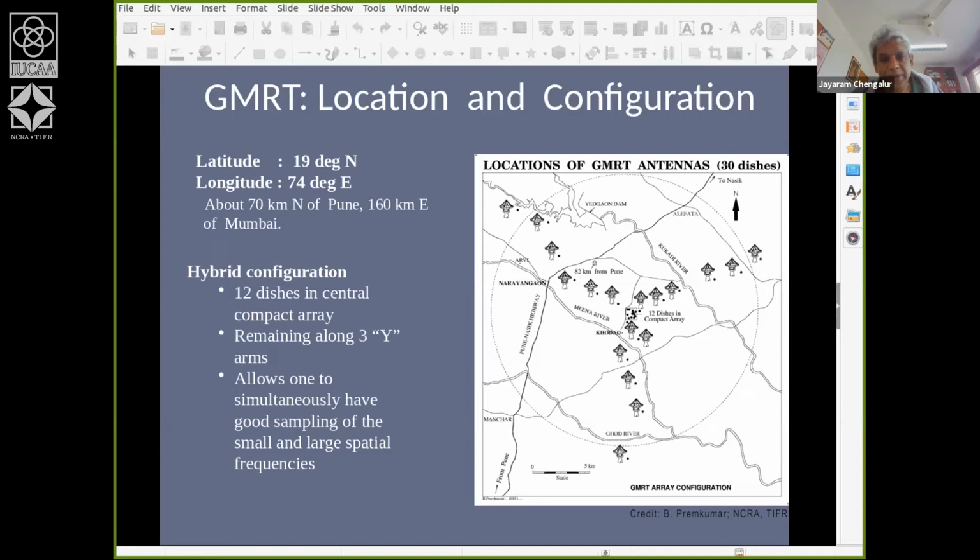So you can see when I put the antennas down in a straight line, the problem of connectivity actually is greatly simplified, because I can run just a single cable trench along this line, and I can lay all the cables that I need to get to these antennas along that trench. If I were to randomly distribute antennas in this 25-kilometer area, I have to dig a separate cable trench to each antenna, and that can be a very, very expensive operation.